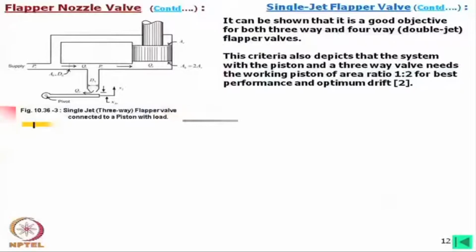You will find that when this piston cylinder is at the central position, it is basically controlling a spool, and that spool should also be in the null position. But due to leakage and error, when this is in the mid position, what it is controlling is not in the null position. So, this null position and that null position may not match. That is called drift.